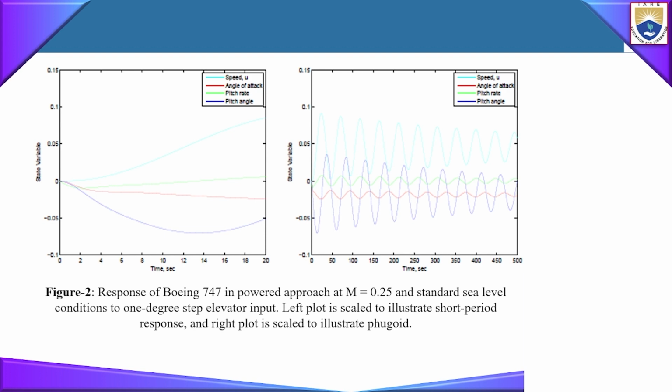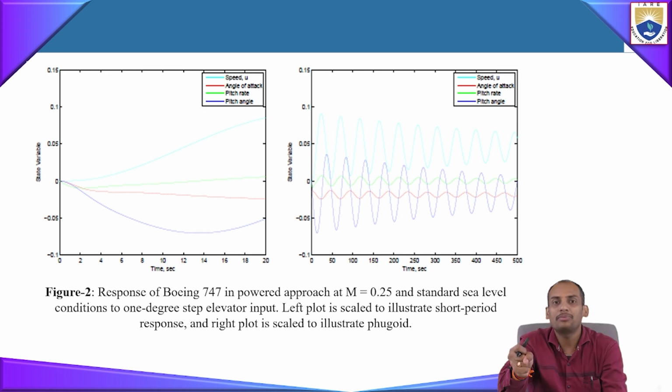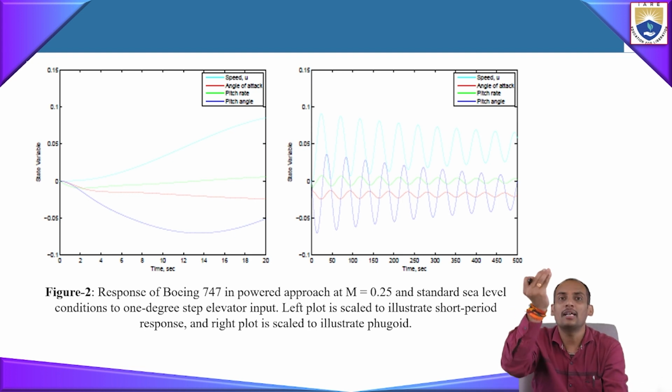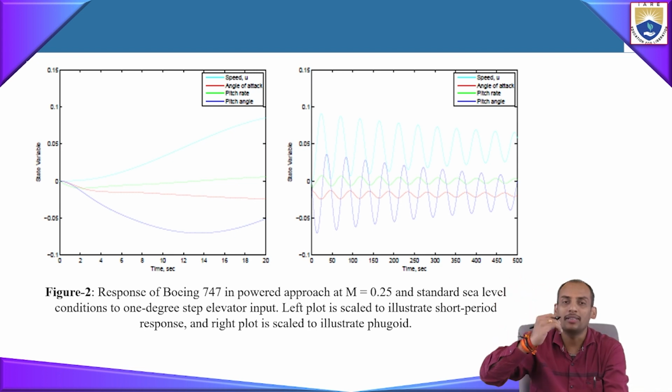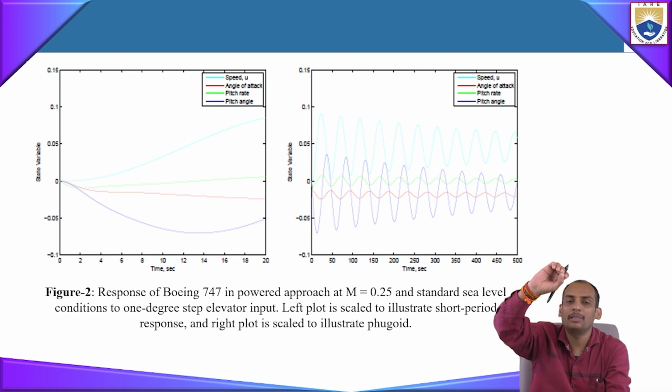If you remember, previously we discussed pitch orientation control and the displacement autopilot. We have given the elevator input in terms of degrees. This much signal we are giving, and for that signal, how many degrees the elevator moves. That elevator movement we discussed in terms of volt per degree: for this much volt signal, the elevator moves this many degrees.